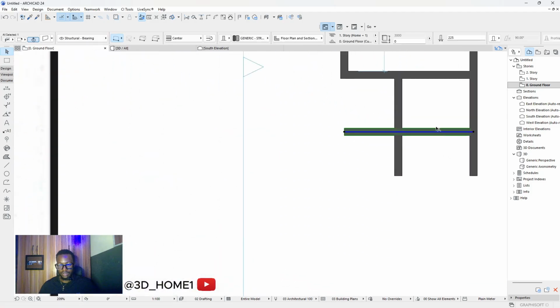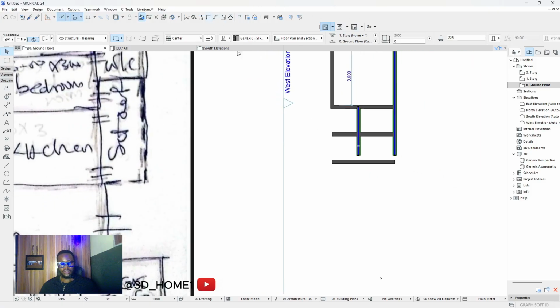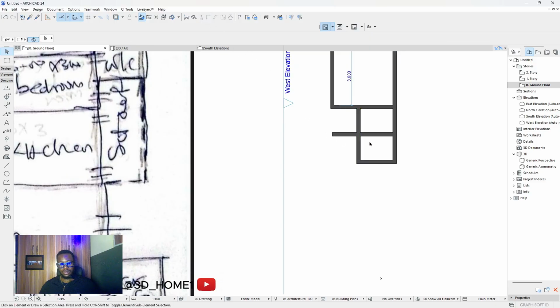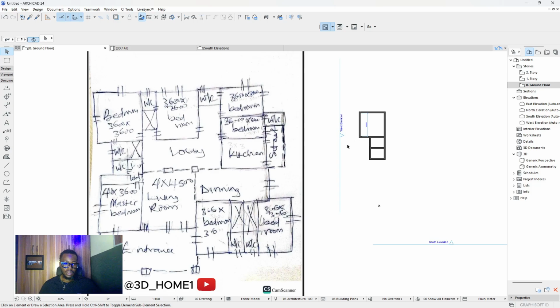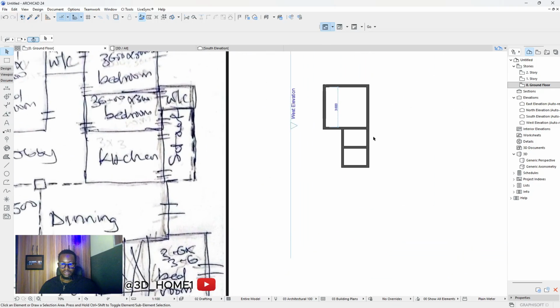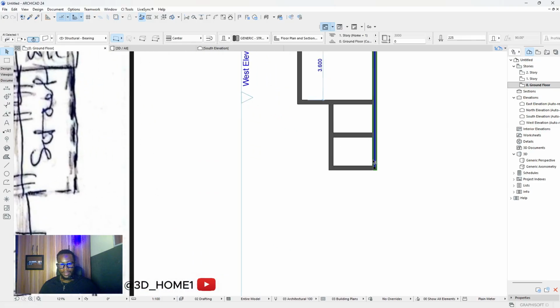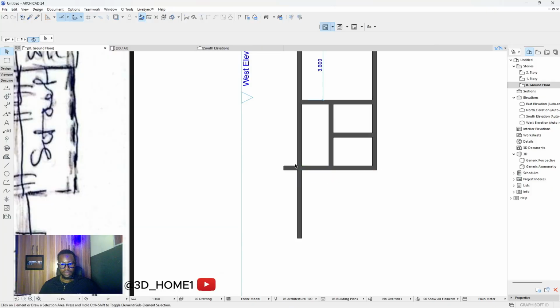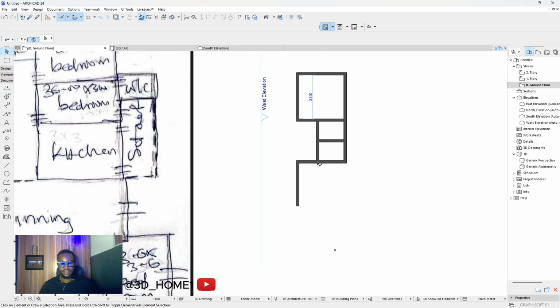So we'll repeat the same thing to this side. That's 1,500. Then we'll click from here, bring it down. This and this, we'll trim it. Trim this. I'll cut this one. And this other side is 3.6 by 4 meter. This other side looks longer while this one is shorter. So we'll make here, we'll drag this one all the way to this point. Drag this one all the way to this point. Delete here, cut here. Okay.